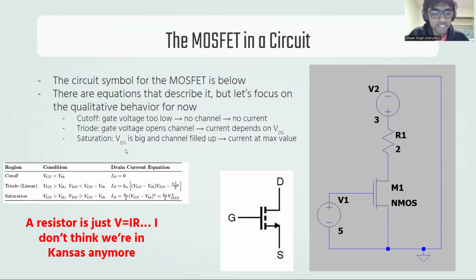The gate voltage is what opens the channel. It opens and closes the channel, but there's no current that flows through the gate, right? Because of that insulator layer, okay? If the MOSFET isn't cut off, there's exactly 0 current.